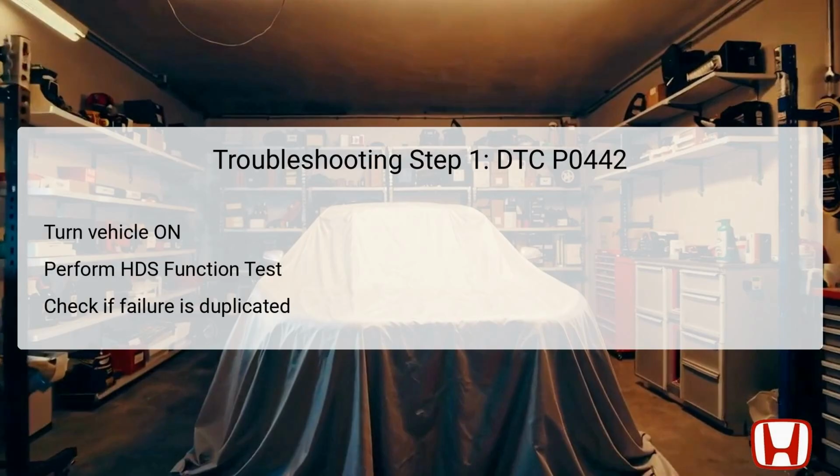The purpose of this test is to confirm whether the detected failure can be replicated under controlled conditions. If the test results indicate that the failure has been duplicated, it confirms that there is an underlying issue that necessitates more in-depth inspections of the EVAP system. The HDS will provide valuable diagnostic readings that can help pinpoint the specific component related to the detected fault.